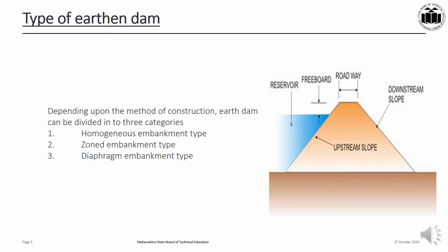Okay. The material used for earthen dams is clay material like black cotton soil, silty clay loams, then sandy materials like medium soft rock, sandy silt, then rock and sand. Cement, steel, lime, and other building materials are used only in small quantities. But earthen material like clay, sandy material, and rocks are used in huge quantity.